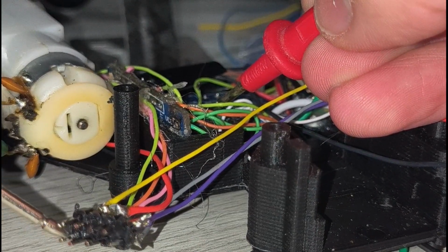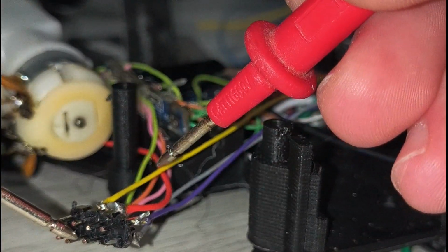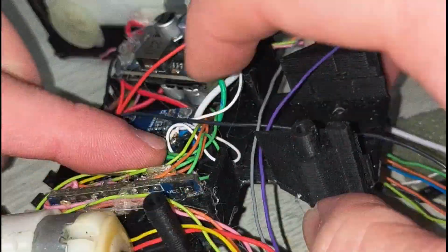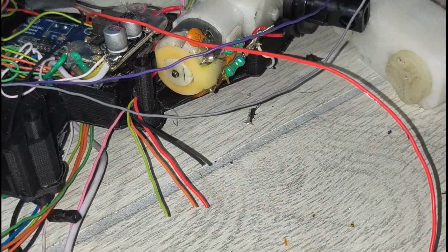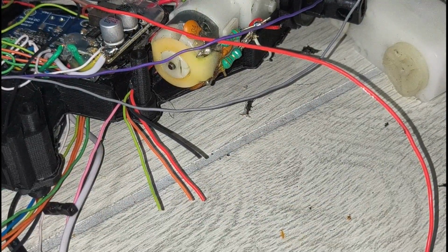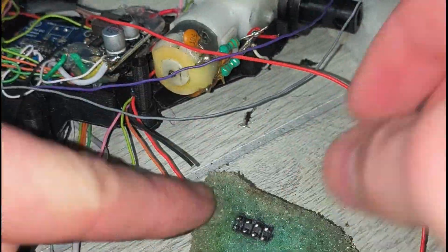Again, you can see some meticulous testing with the multimeter. This is a very good practice when building a Robosapien if you don't want to make a big expensive oopsie. So we'll just copy the arm connector on the other side and do some cable routing and pass those PWM wires through the back, and we'll keep those other purple wires ready to be connected to the motor controller. But for now, we're just checking for shorts and putting together the connectors and making sure that everything goes together properly.